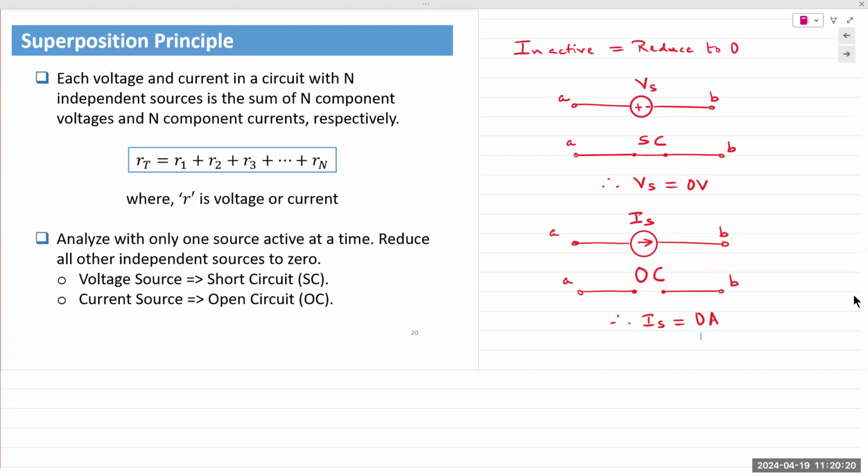Don't do that. What it's asking you to do is remove or disconnect the power supply from the circuit, and short out or place a wire where the terminals of the power supply were connected. So you're shorting out the place on the circuit, not the power supply.